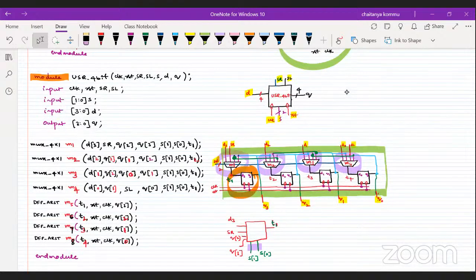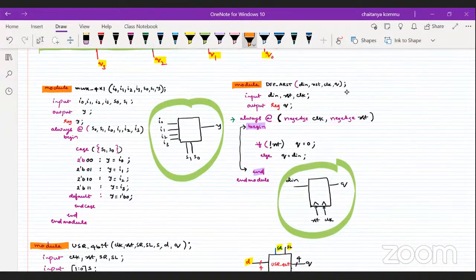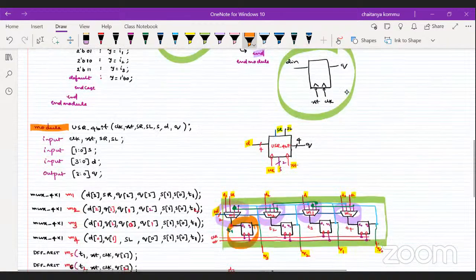Okay. So there is a possibility of writing the multiplexer differently, because the multiplexer is also not a fundamental element. We can write it in any modeling style. Suppose you feel that this is a very big representation, then go for a simple dataflow modeling. It's the simplest one. So then you can call it. What is inside the multiplexer does not have any impact.